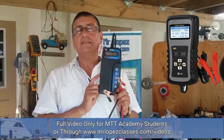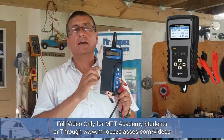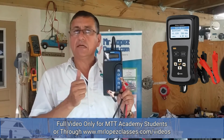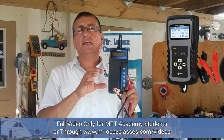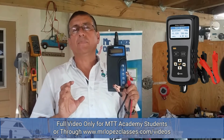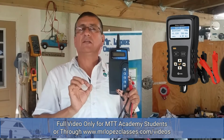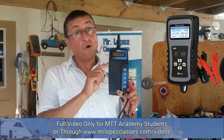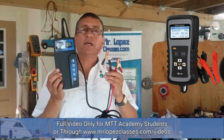This load tester is excellent because you can apply the load specific for that battery, because this system asks you the type of battery, if the battery is gel or lead acid, if the battery is connected on the circuit, if the battery is disconnected outside of the boat or the engine, and immediately explains in the report if the battery is good, if the battery needs charge. If the alternator is not working, this element analyzes if the problem is not on the battery, it's on the alternator. This is more accurate than the analog.